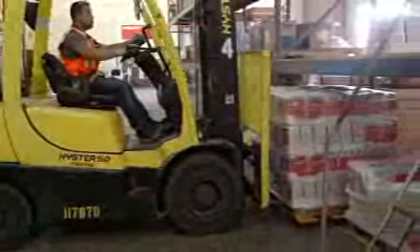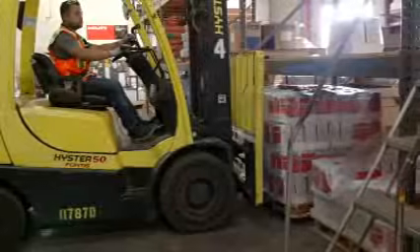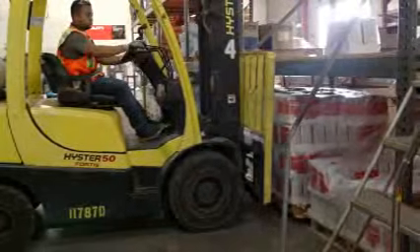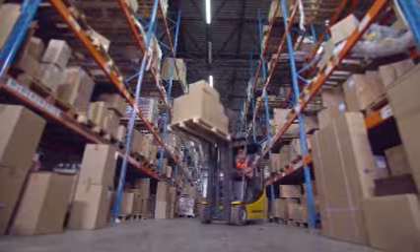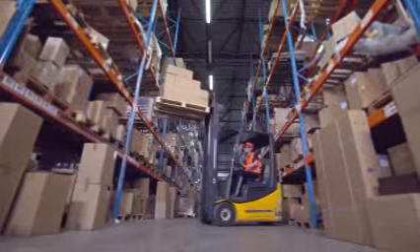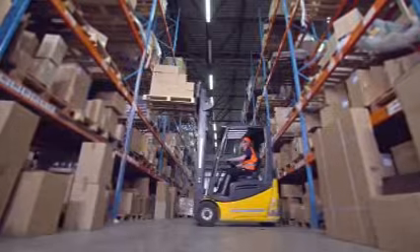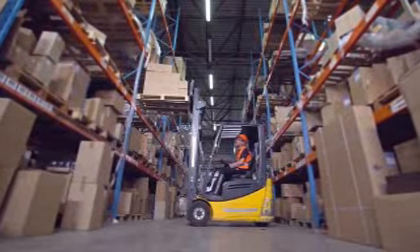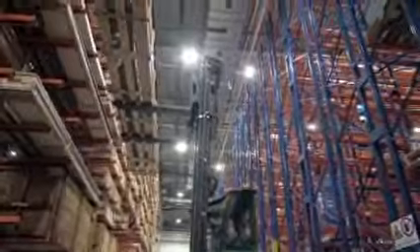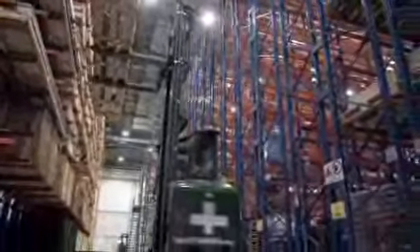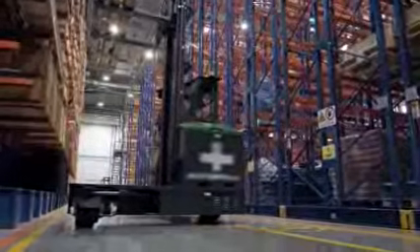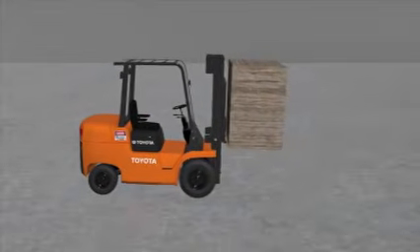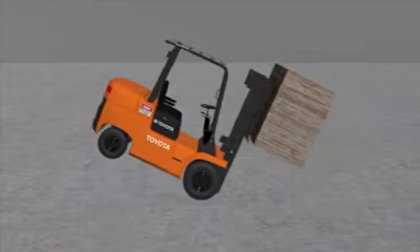The heaviest loads should be on the bottom tier and the lightest loads on the top tier. Reduce the load below capacity of the reach truck as the mast is fully extended. Carefully extend the reach mechanism of the truck forward when depositing the load. Use extreme caution when tilting a load forward or backward, especially when high tiering and on the top tier. Improper tiering of a load can cause a truck to tip over.